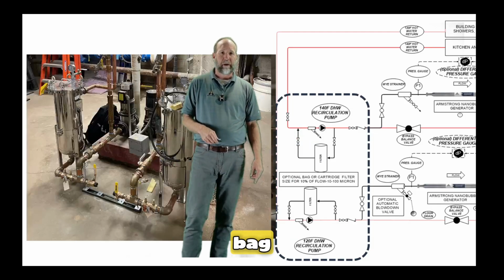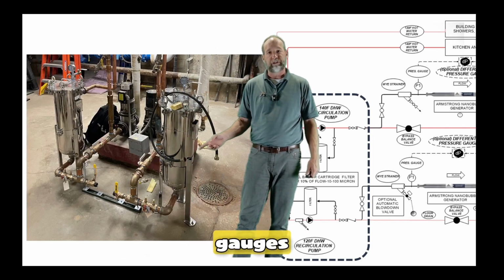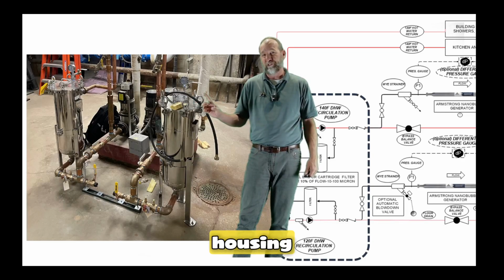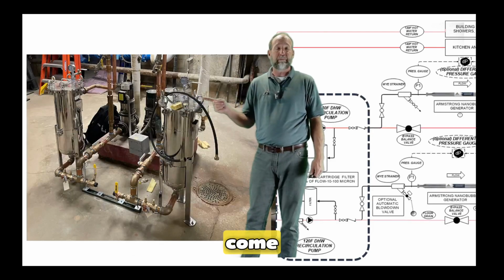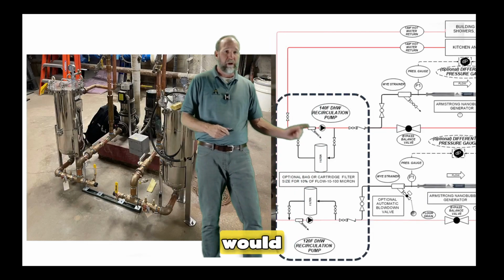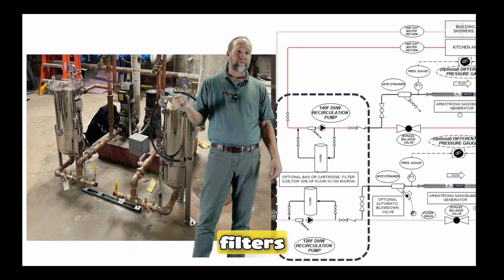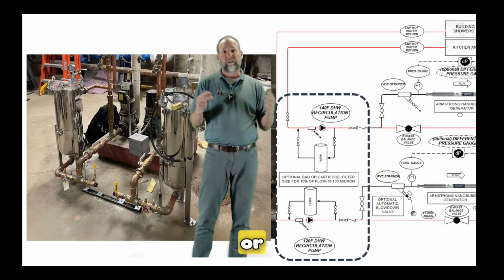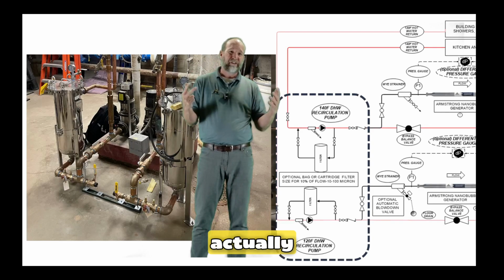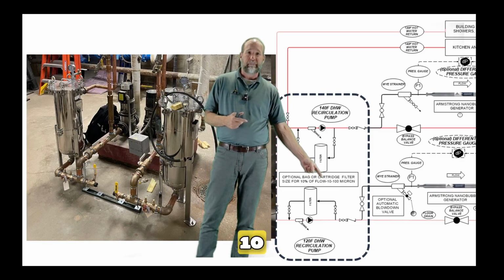These types of filters, the bag filters I was telling you about, are pretty slick because they typically come with differential pressure gauges, either ports on the filter housing for gauges, or for sure add differential pressure gauges. And also these bag filters typically come in different micron ratings. What I would suggest is that you start at 100 microns, okay? And also the good thing about filters, bag filters in particular, but cartridge filters as well, is that as a filter gets plugged or as sediment and things get built up in it, it actually filters better than it started, okay? And so don't start with a super fine like a 10 micron, okay?